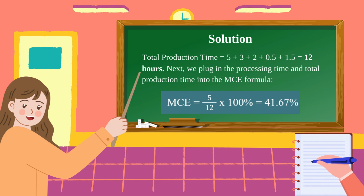Here are the solutions. The first step is to calculate the total production time. Total production time equals 5 plus 3 plus 2 plus 0.5 plus 1.5, which is equal to 12 hours. Next, we plug in the processing time and total production time into the MCE formula. MCE equals 5 divided by 12 multiplied by 100% equals 41.67%. Here, we get an MCE of 41.67%. This means that company B has a better process efficiency than our first company, but there's still room for improvement.